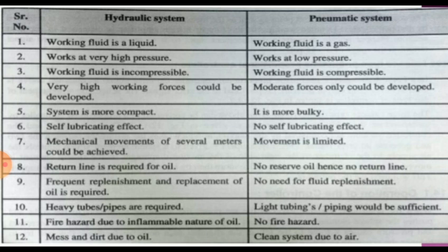In a pneumatic system, the working fluid is compressible and only moderate forces can be developed. A hydraulic system is more compact, has a self-lubricating effect, and mechanical movements of several meters can be achieved. A pneumatic system is more bulky, has no self-lubricating effect, and movement is limited.